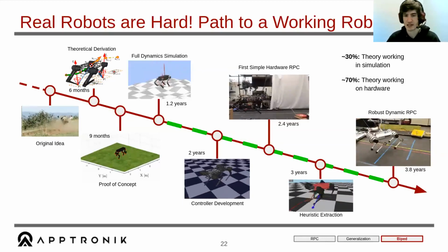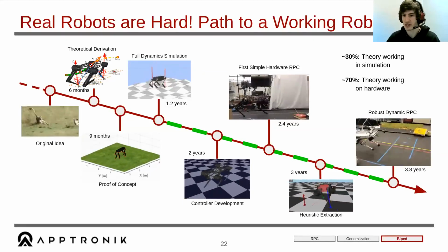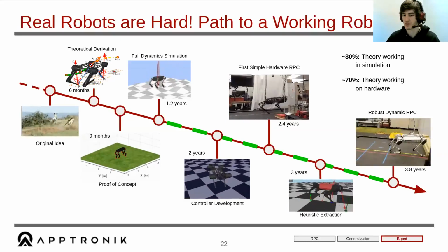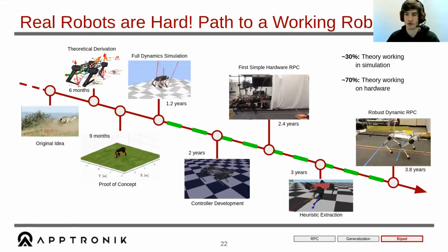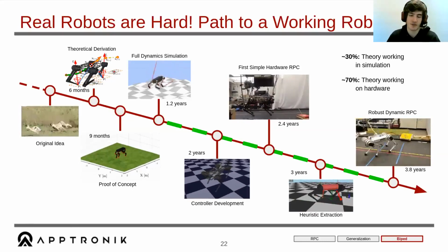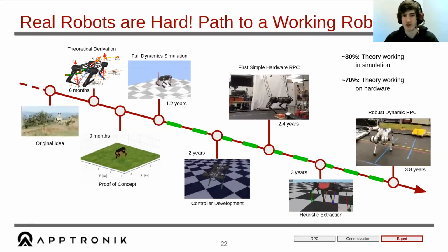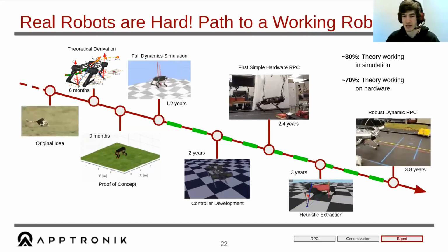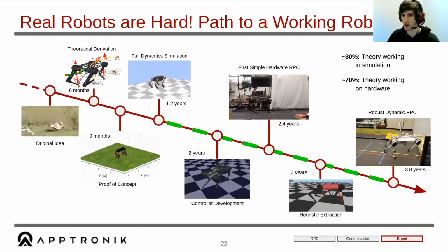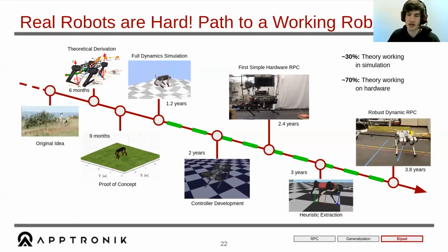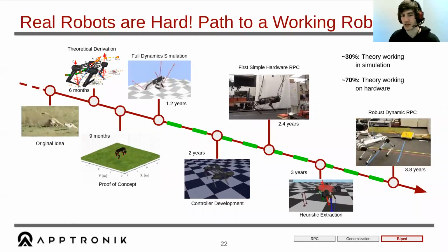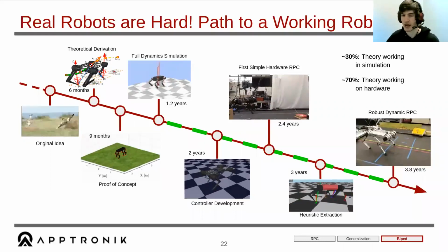And the reason for that is the linear version isn't optimizing for footstep placements. So you're simply doing some kind of capture point or just stepping wherever the robot ends up stepping and trying to use forces to compensate for that. Whereas in the nonlinear version, you're optimizing for footsteps and forces. So if you need more torque on your center of mass, instead of having to apply a ridiculous amount of force, the optimization would simply choose to step further out.